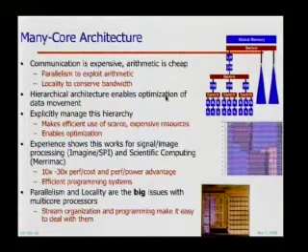But in doing that, what we quickly find is that the arithmetic isn't the costly thing. It's inexpensive in terms of die area. It's inexpensive in terms of power. The costly thing is communication. And so while performance comes from parallelism, and that's inexpensive, efficiency comes from locality, because communication is what's expensive. The way to get both parallelism and locality is to build a machine that exposes the expensive thing, communication. You want to expose that communication.